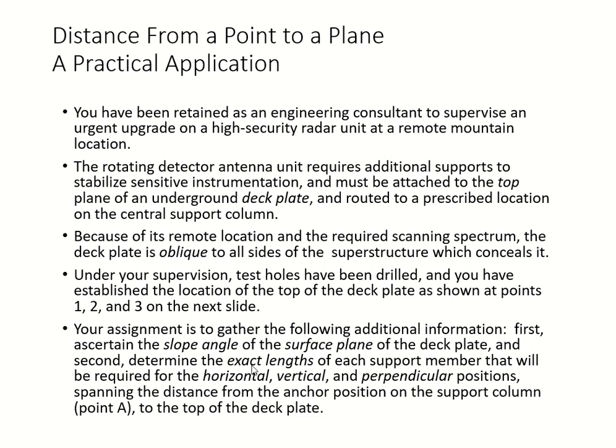This is a pretty long problem, so don't worry about it. Every time you get a very long problem, make sure you identify the planes, what the views are, and how many points you've got on these planes. All other things, who cares? You can pinpoint all that you need like this. Right now I know that there are 3 points, I know that I'm dealing with an oblique plane, a deck plate, and it's set so. This is how you scan the key points of your problem.